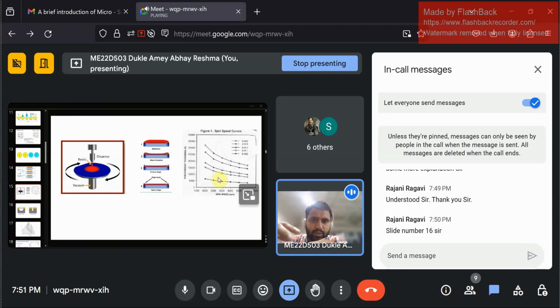Then whatever areas you need to keep, you harden them. That step is called photolithography. You have a mask, and the mask has the areas which you need to keep and which you don't want to keep. The areas which you want to keep, you harden them, and the areas which you don't want to keep, you leave the resist as it is. Then you wash off the photoresist.